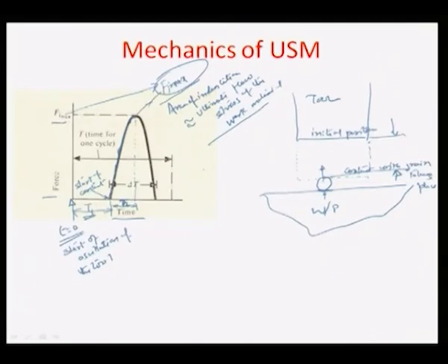And then of course, once the material has started flowing and the grain starts going inside, the force on the grain comes down, okay, it comes down, and the tool really after this point does not face much force because the material is in the flow state. Okay. So, the force comes down, and then after a while the tool leaves contact. So, the force is 0. Okay. So, it comes down here and somewhere the tool leaves contact, and that happens, let us say, after time t3, okay.